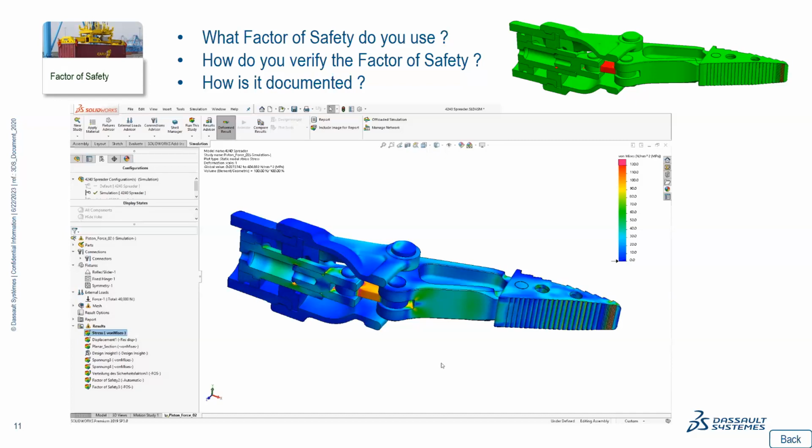If you adapt your color scale to the elastic limit in von Mises, you will see that you should not go up to this elastic limit, because when you do, you start to plastify your steel, so you really deform your material, and you start to damage it. So this is one way of interpreting the color change on the scales. I hope it answered your question.